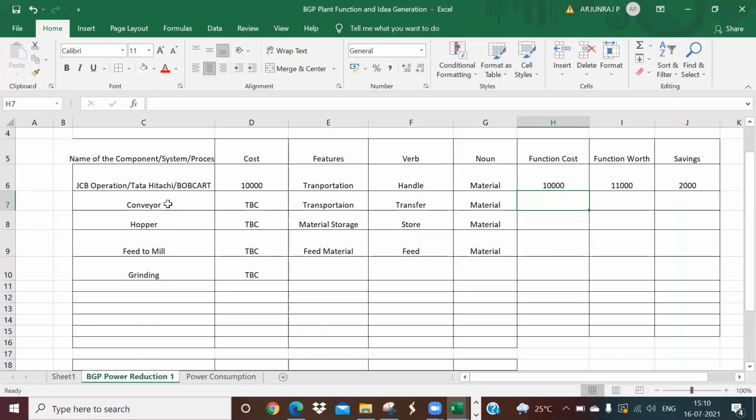Even so, you have different ways to transfer the material. Whether those things are capable of carrying the particular load of your material, it is both load versus speed. At what speed is it going to travel? And against that, even the life of the conveyor is very important. What is the durability? What is the life? How many hours is it going to last? You need to consider everything when you are going for the selection.